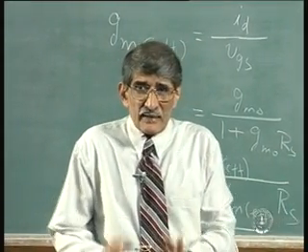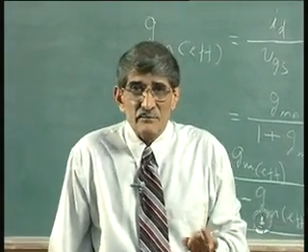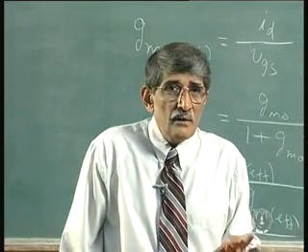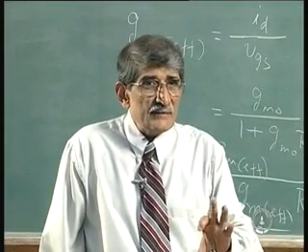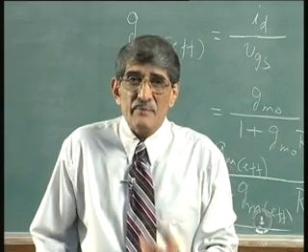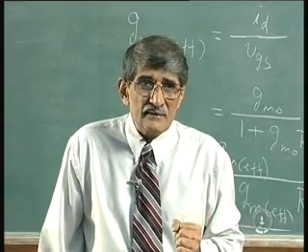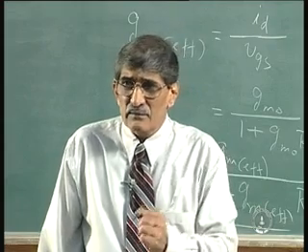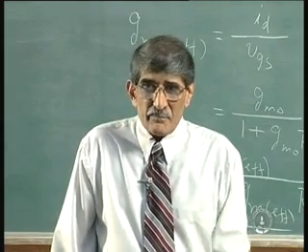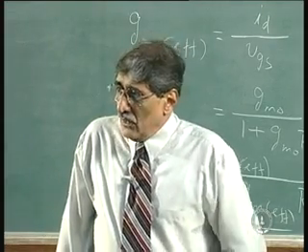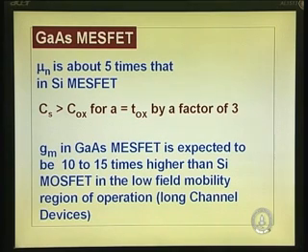We are not worried about current so much, we are worried about transconductance, because that gives how much change in current for a change in voltage, which gives the driving capability of the device. So Gm is the most important thing, whether you talk of bipolar, MOS, MESFET, whatever it is, the comparison should be that. So, in a long channel device there is no problem.